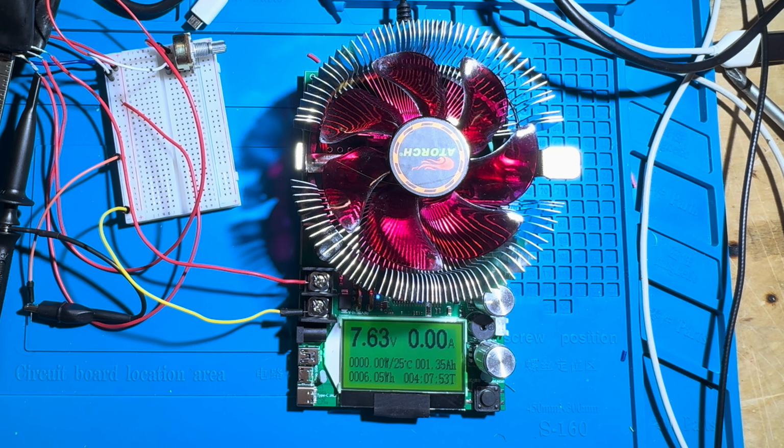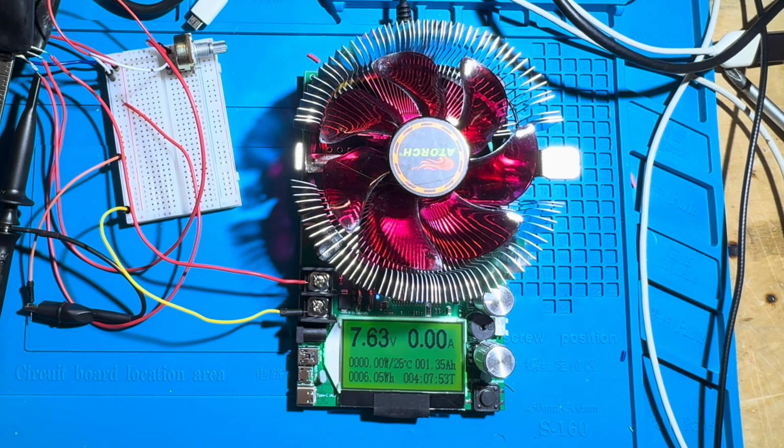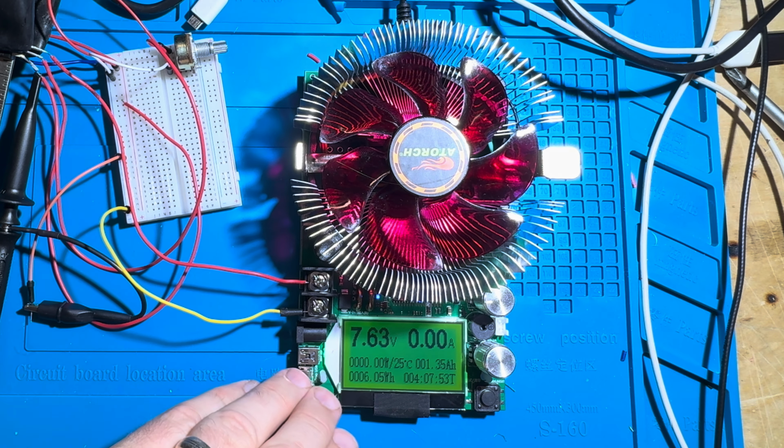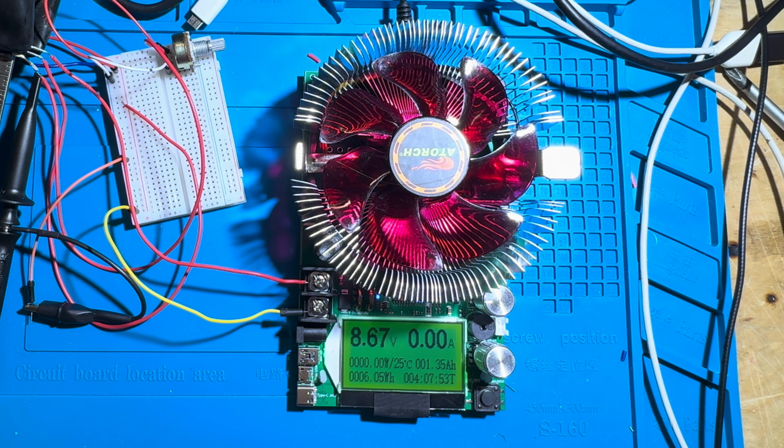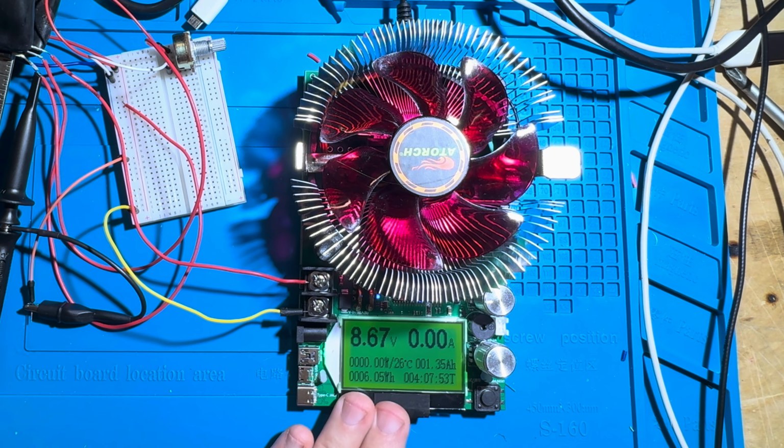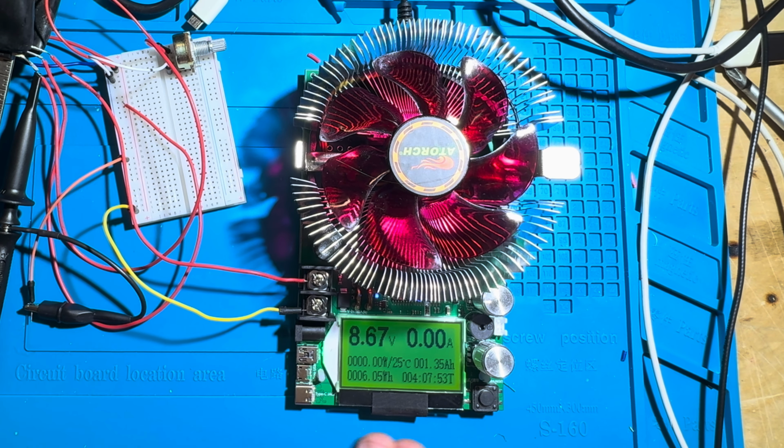So now I'm at 11 volts of gate voltage, and we have 7.63 volts across our load. So that means we're sinking almost 5 volts across the MOSFET and almost 8 volts across our load. So this MOSFET is starting to conduct more and more. And then I'm going to turn all the way up: 12.2 volts. I don't know how we're getting 12.2 volts. And we're getting almost 9 volts across our load. So roughly 3 volts is being sunk across the MOSFET and 9 volts across our load. And this is with 0 load, so our load really isn't doing much of anything. It's sinking a very minimal amount of current, not even registerable.